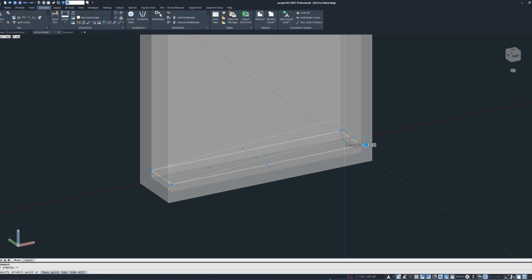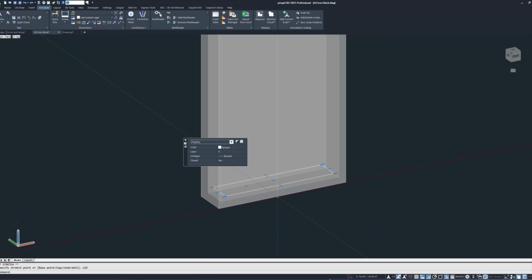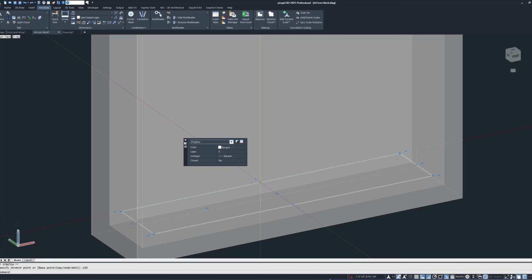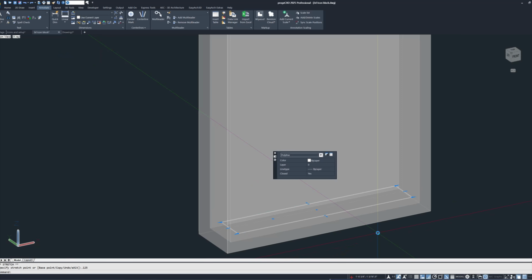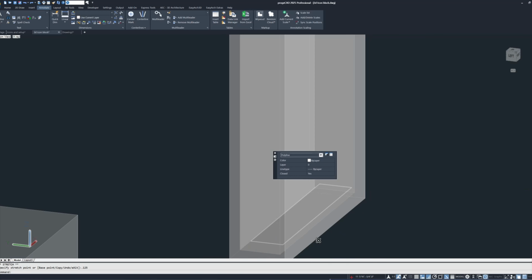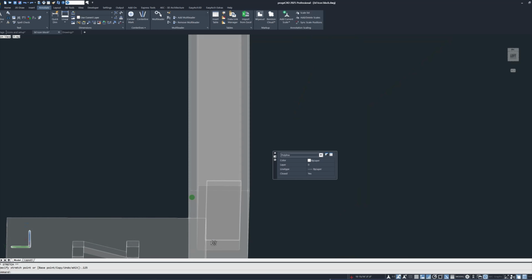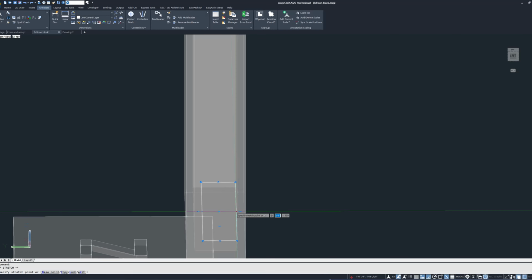Since the polyline is within the bounds of the solid, it may be best just to grab the line's snap points. We need to offset the boundary of this polyline to 1/8 of an inch so we can subtract the space for an opening. All we need to do at this point is to move the front line to the outside of the face.